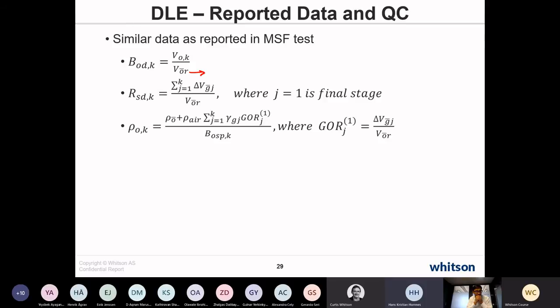When we do it, we use the DLE, take the stock tank oil density, and then back calculate the density to the saturation pressure. With the multi-stage flash we do the same, and for the single flash, or for the CME, we do the same. So we report 3 different densities taken from the experiment. And if the laboratory is just reporting one, I ask the service company why they are doing this, because we are measuring the Anton Paar high pressure density. We believe that's the true value.